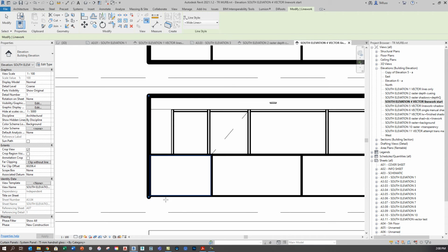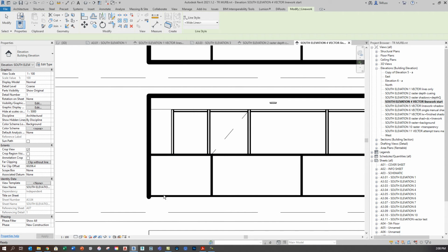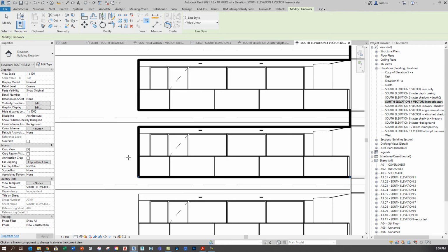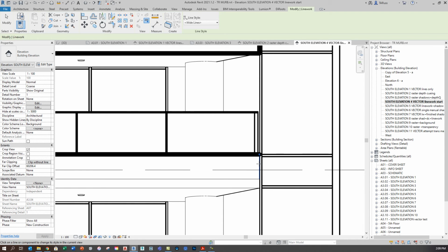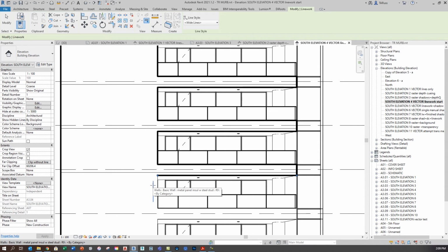Once you've done that, you also have the ability to modify a little further with these little blue dot grips. If for whatever reason this hadn't quite been in the right spot or maybe went too far, I can just grab that little blue dot grip and pull it back so it goes to a point that I may have wanted. I'm just going to do a few more clicks here. I won't do the whole procedure. I've already got one finished in a later set, on a later sheet, but it's just going to look like that. I wouldn't suggest trying to do a lot of different line weights. You might just need maybe 3 or 4 to add some emphasis on foreground versus background. And you can also set up some custom line styles that maybe have a bit of a gray tone to them.